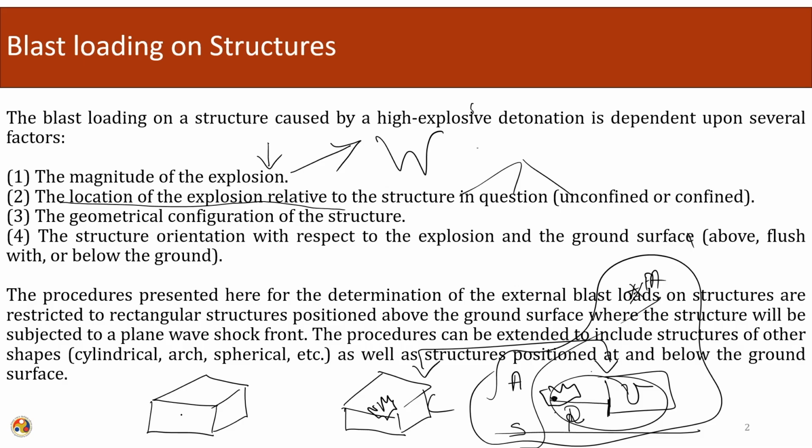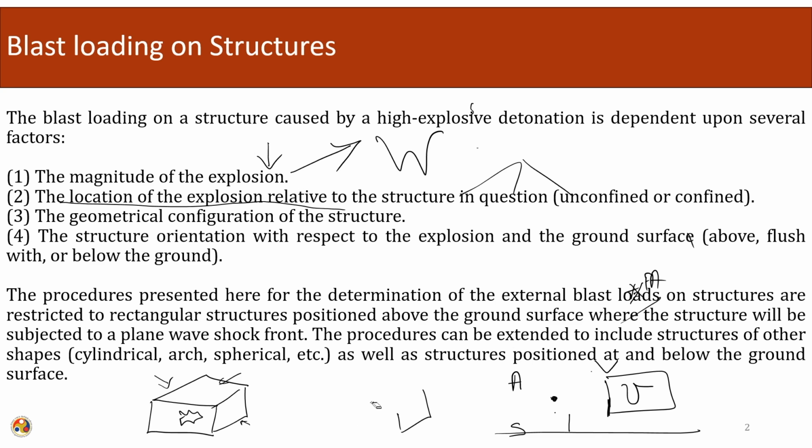The same is true for the confined blast. In a confined blast also, depending upon the confinement, it will be either fully ventilated, partially ventilated, or fully confined. Depending upon this factor, the attenuation or amplification of the pressure will occur. So in both cases, the relative location between the blast loading and the structure plays an important part.